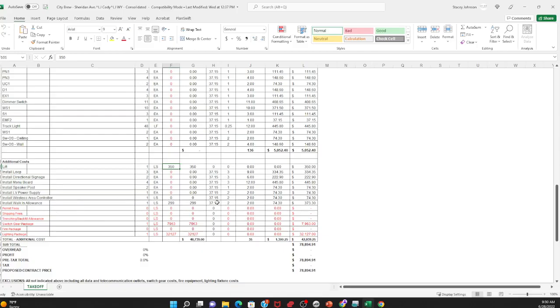And then there was a walk-in, like the walk-in freezers. There's always additional, like heat tape and all kinds of crazy stuff they have to do when they install coolers and freezers. So I just gave them what's called an allowance. I give them an allowance because I know they have to spend something on it, but I don't know the exact amount. So you give something as opposed to nothing, and let the electrician adjust if it is appropriate. But always account for it.